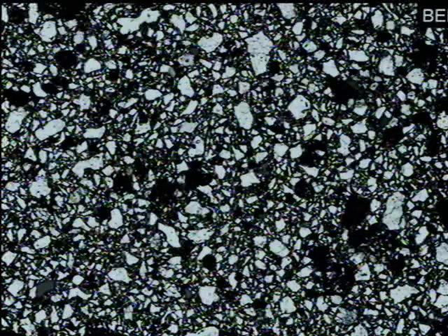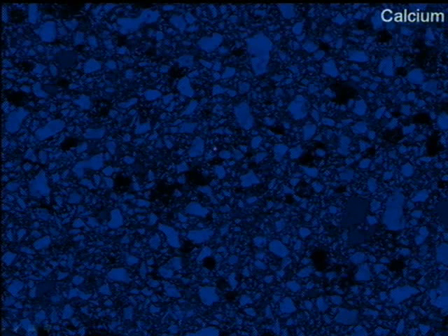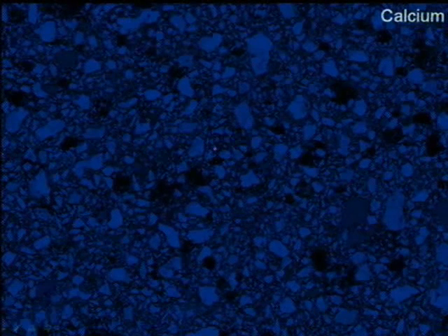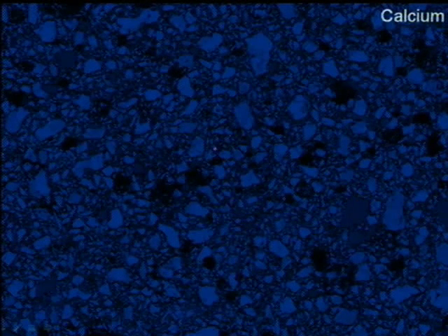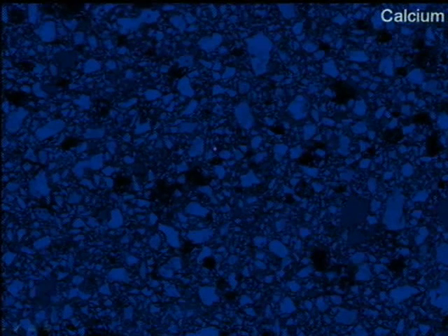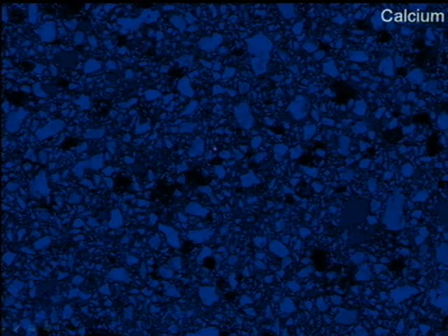Now if we stop there, we would basically just be able to get a little bit of information about the size and the shape of the particles, maybe a little bit about the density of the particles, but we can actually do something called energy dispersive X-ray spectroscopy. This will basically give you the chemistry of the overall system. You can basically get a signature of what chemicals are at each point inside of the overall picture.